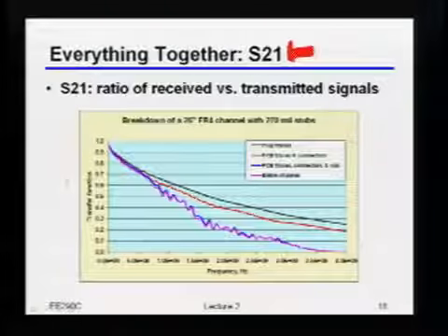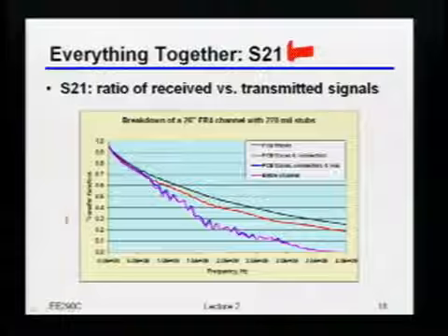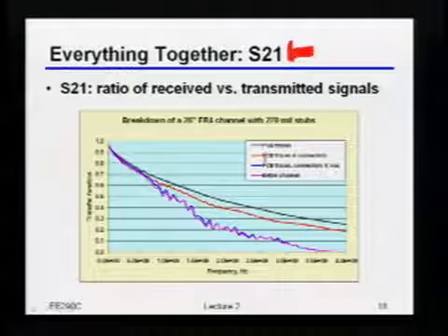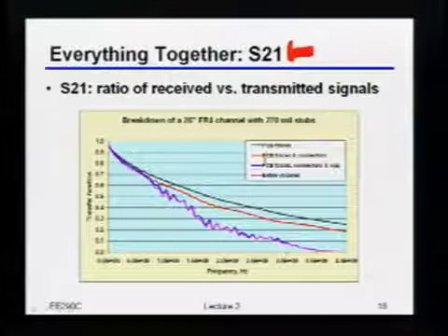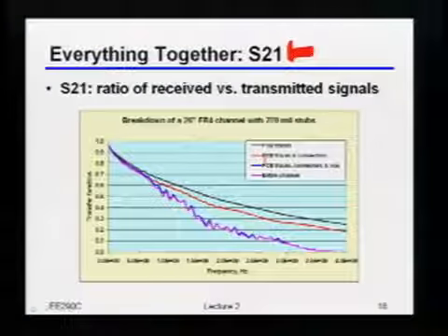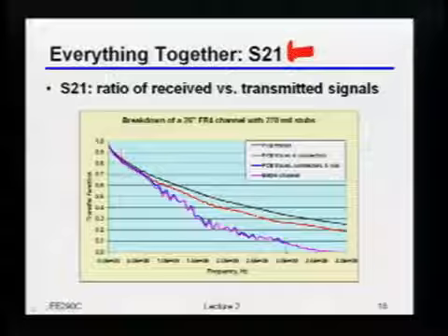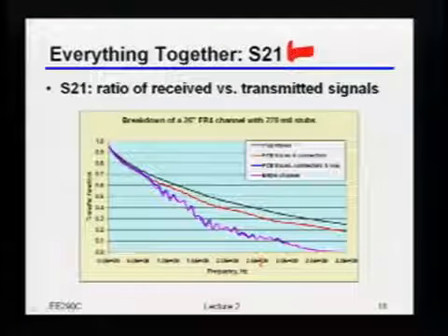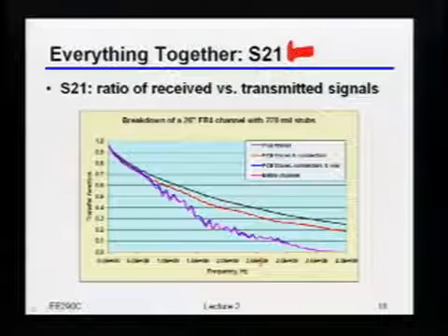As you can see, there are lots of different types of channels that you may have. You can, of course, take different components and try to cascade their S21s, as long as you're careful about the matching and things like that. If you do that, then you can get an idea of overall what your channel actually looks like from a signal integrity standpoint.